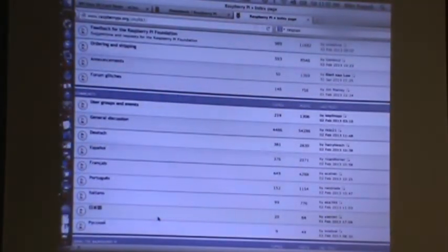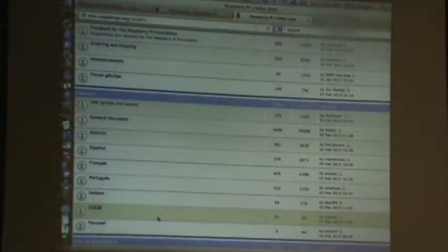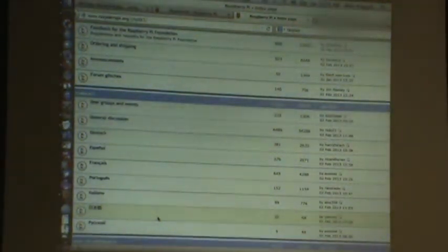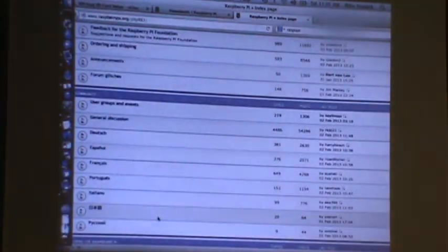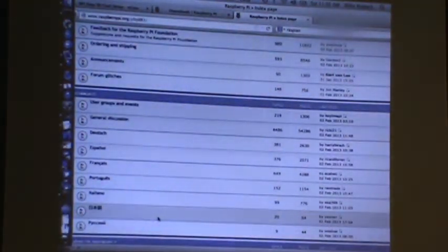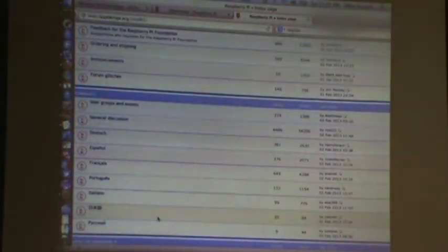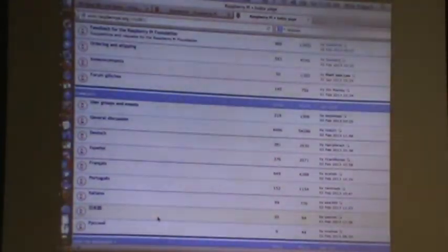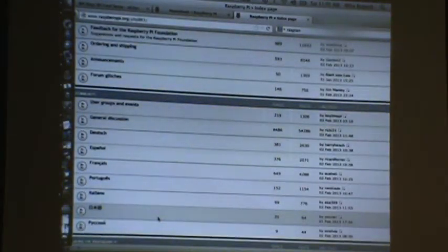And then you just copy it over. You can find info on how to do that, though. It's usually setting up a cross-compile environment, assuming that you're doing it essentially from scratch using instructions. It takes a while, it's kind of a fussy pain in the rear, but once you're done and understand your build process, it just works. Yeah, and it's much faster than trying to do it on the Pi.